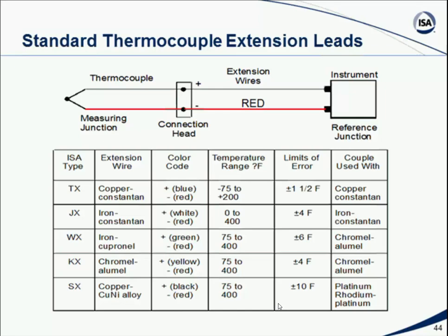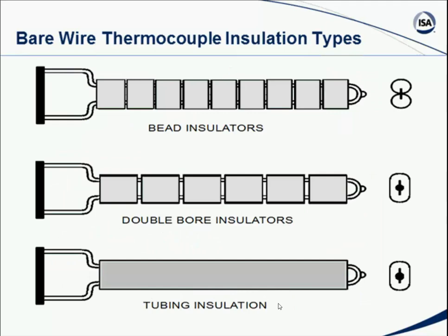But if you are going to run a thermocouple signal any distance, you have to use extension wire that matches exactly the thermocouple itself. If you get it wrong, you will not get correct readings. Now, the design of a thermocouple is very simple. Here I'm showing three simple little examples. These are greatly expanded. We're talking about something that's actually, in the usual case, just an inch or two long.